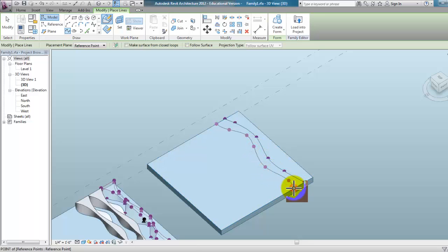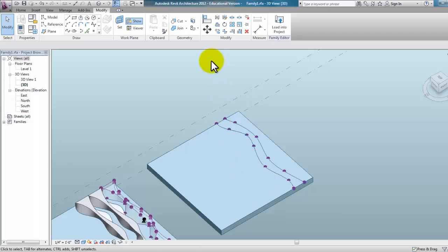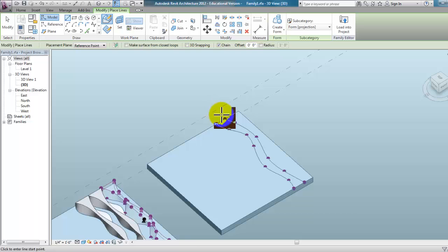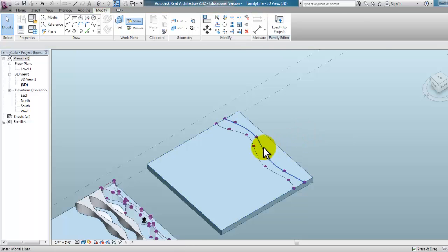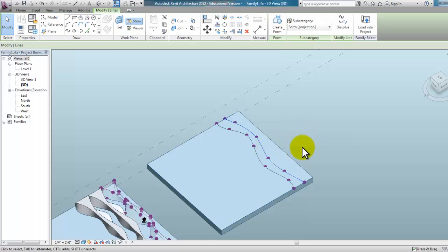Use the spline through points to create here a spline from one side to another of that top surface, and then use it again, the spline through point, to create another second side of that spline, picking points on that surface, and then use the line tool there to connect the two end pieces, the two end splines. Now we can select here the whole form, the two splines and the two ends.